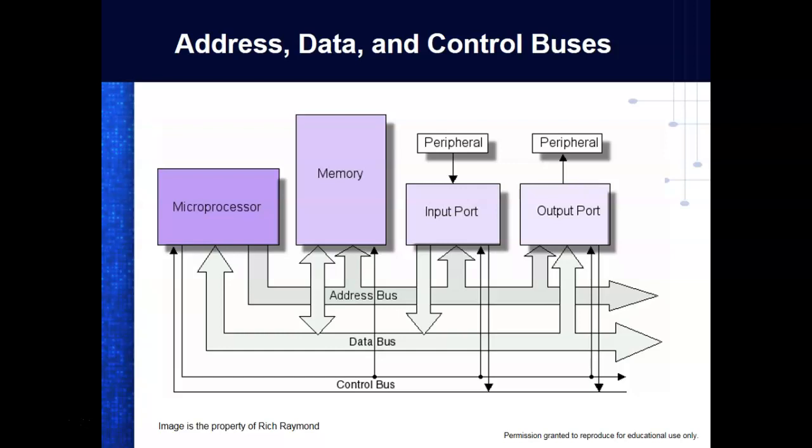So what we do is we have 3 buses, and we'll look at that later in a minute. We have what we call an address bus, and this is a binary bus. We have circuitry that's looking at the address bus, and we call these address decoders. So the mail person is an address decoder. We're not communicating with the mail person. What do they do? They compare the address on an envelope to the address on the side of a mailbox.